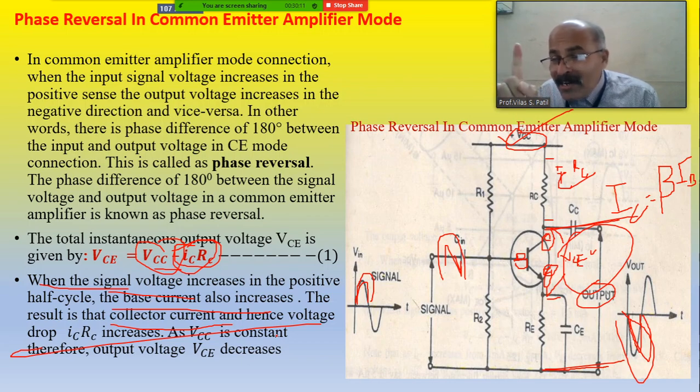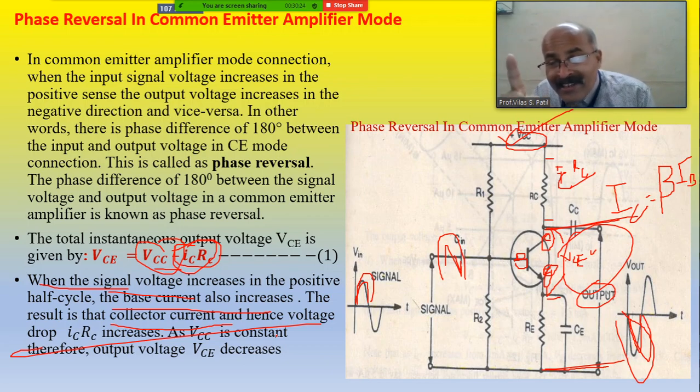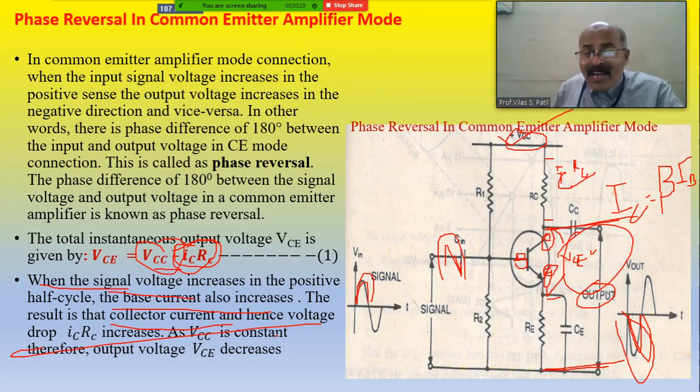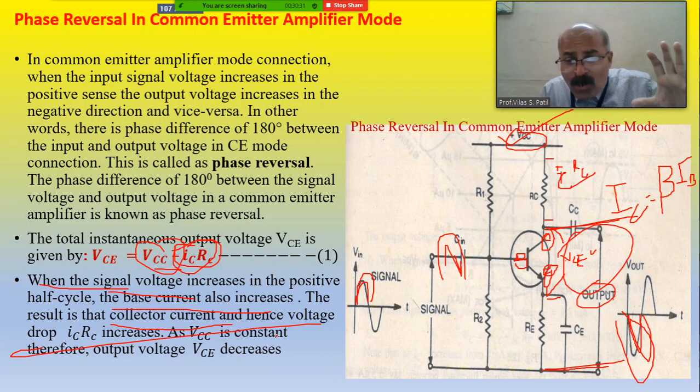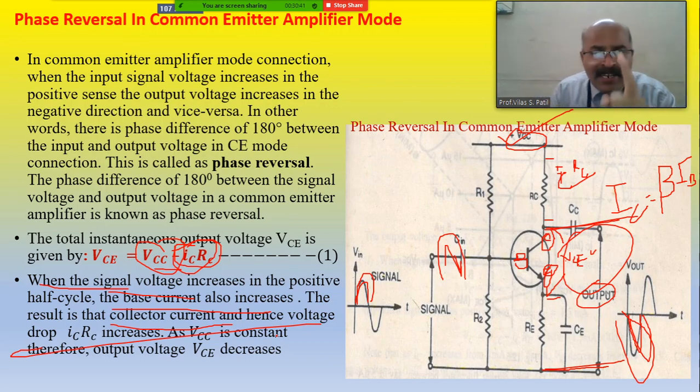This means that the common emitter transistor amplifier shows phase reversal between input and output. This gives the proof that the common emitter transistor amplifier operates with phase reversal, and introduces a 180-degree phase shift between input and output of the transistor amplifier, and this has been explained mathematically.